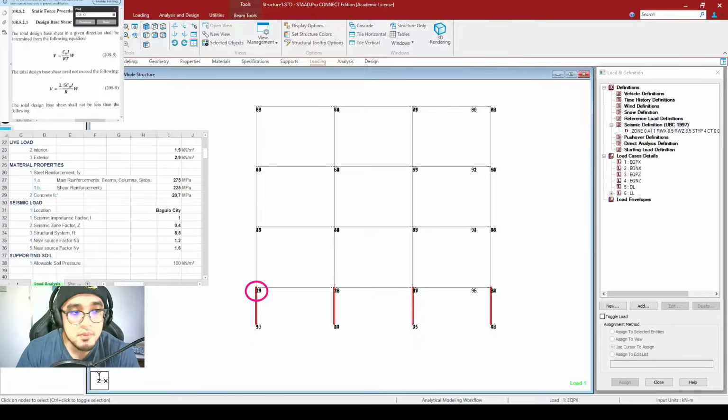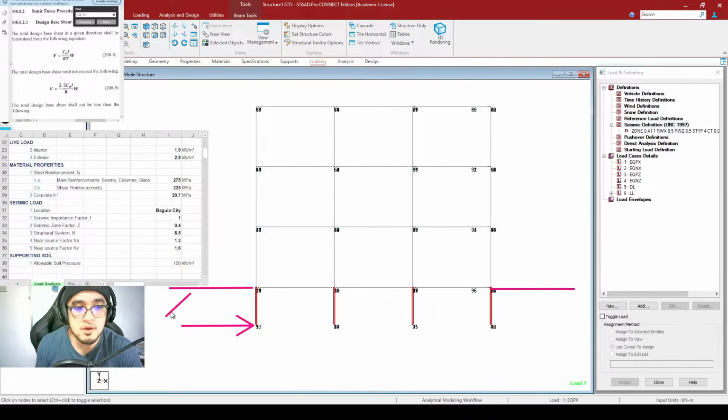And the second approach is for us to leave it as is. So with that way, guys, we are to assume that the base shear is to be located here. And with that, guys, we are assuming that this soil profile right here, so once again, this is to be your soil, we are assuming that this particular soil right here is incompetent for the base shear to be transferred at this particular location right here.